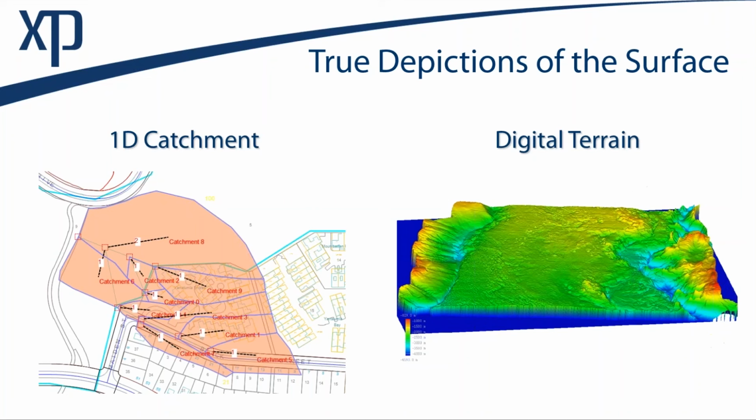Today, accurate terrain data has become widely available. There are a lot of reasons to have accurate terrain data, whether we're doing 1D or 2D modeling. A good 2D surface representation allows us to manipulate 1D elements. If we're just doing 1D modeling, I may want to lower some node inverts relative to the surface or tie the node spill crest to the surface.